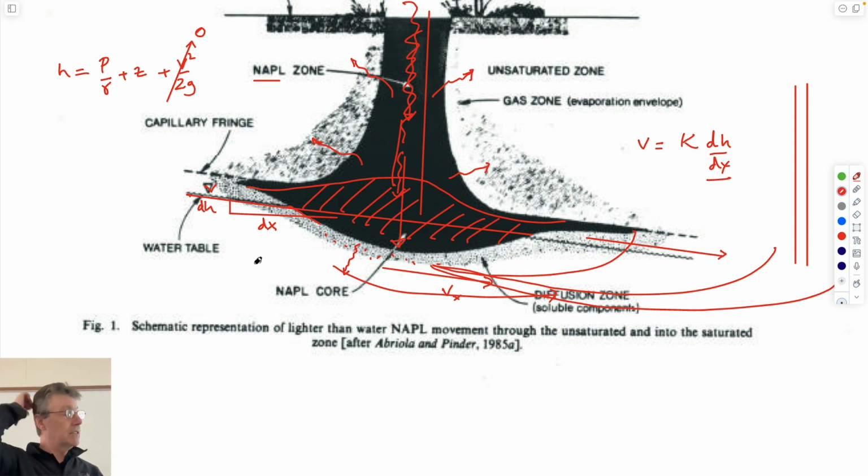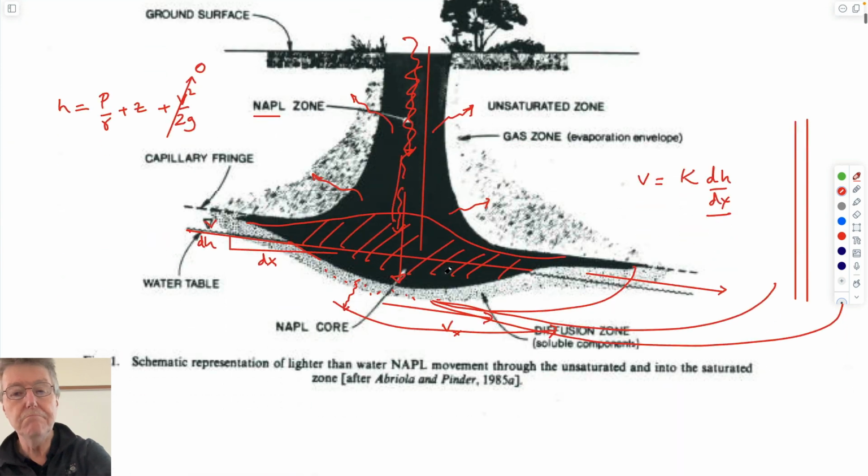So we'll frame most of this class in talking about non-aqueous phase liquids, one, because it's the most important contaminant hydrology problem of our time, and secondly, it encompasses all of the other behaviors that we might want to look at. If we want to look at acid mine drainage, if we want to look at radionuclide transport from repositories, that's a slightly easier problem to deal with because we're dealing with single phase flow with radionuclides carried downstream. Here we're looking at two-phase flow. So it starts off being an innately more complicated problem.